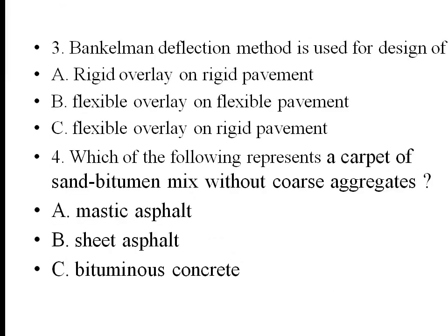Third question is Benkelman deflection method is used for design of. Consider it is a flexible pavement, and for the design of an overlay on the flexible pavement we need to calculate the Benkelman deflection values. It is used to resist the wear and tear of the pavement and it is used to measure the deflection on the pavement. So the answer is B, flexible overlay on flexible pavement.